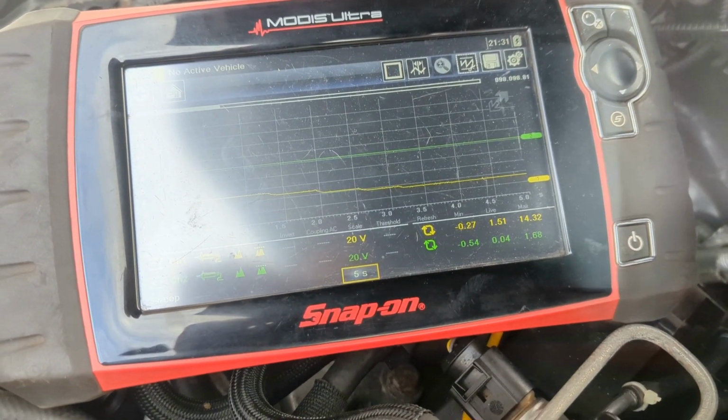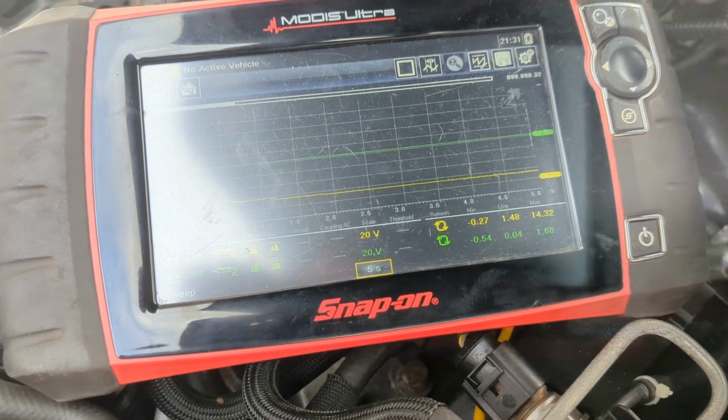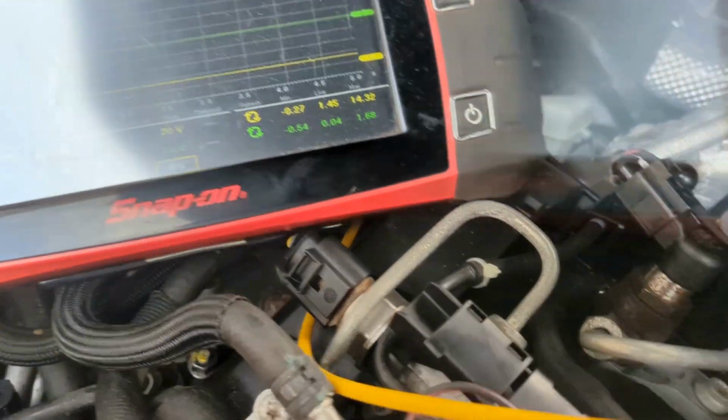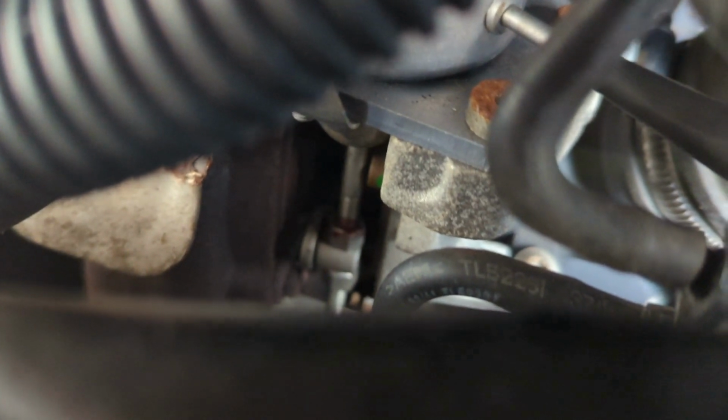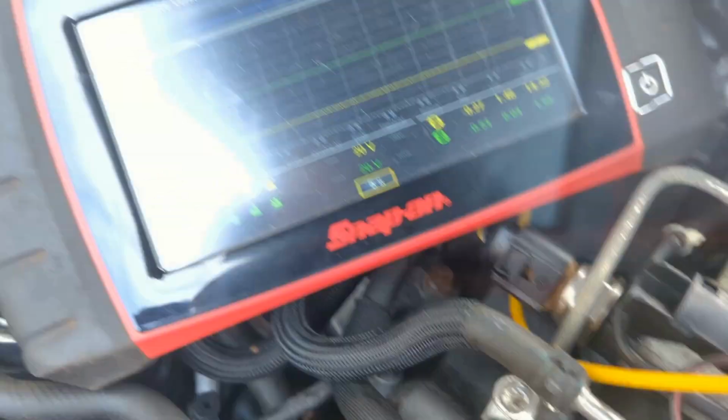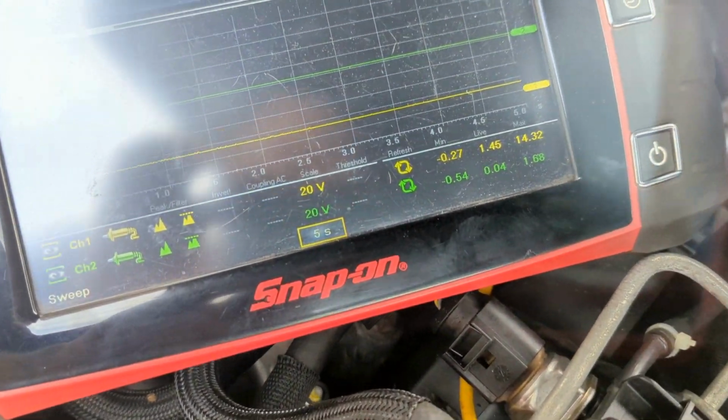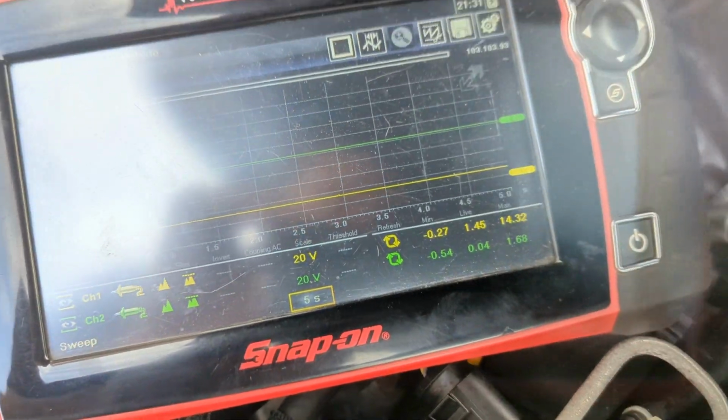What the signal drops to. Got it. The arms there. If I release vacuum, it moves. I don't think there's enough movement in that. And that should drop to less than a volt for me, definitely.